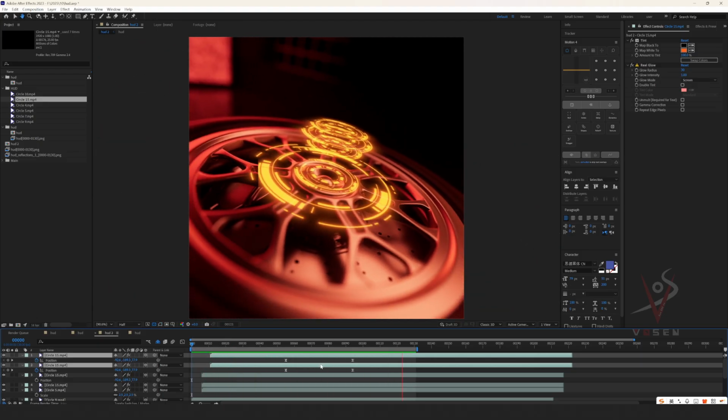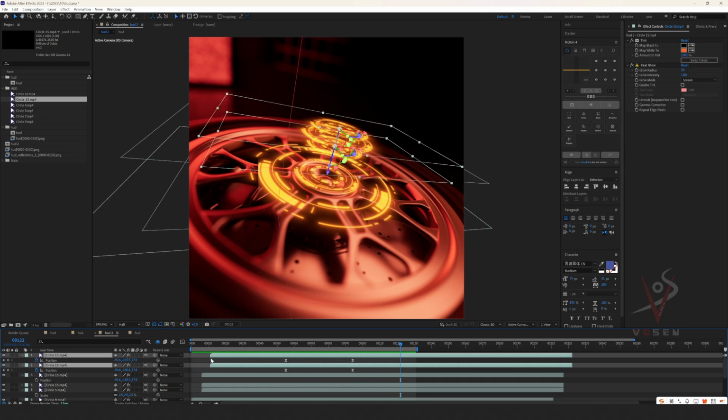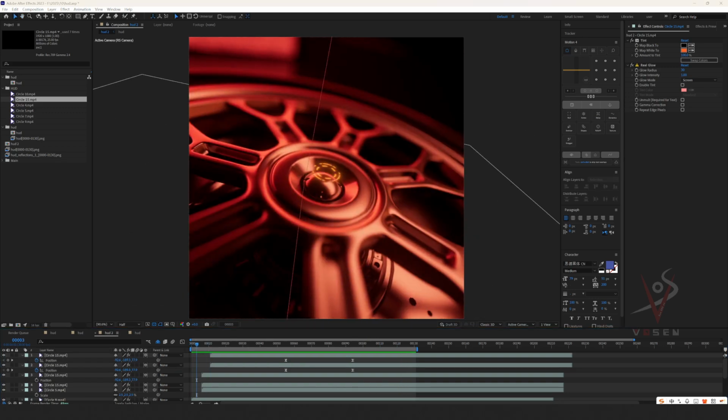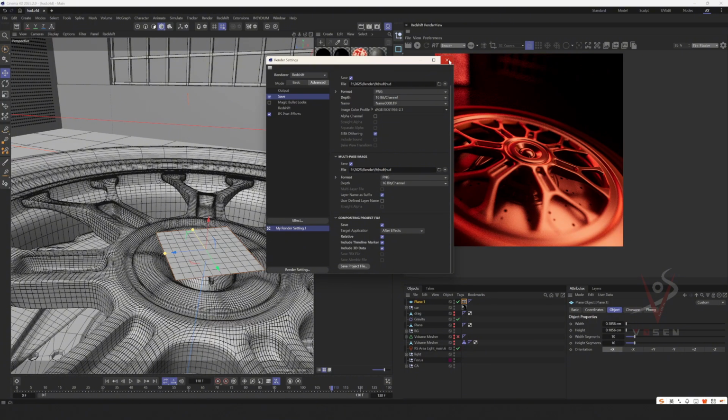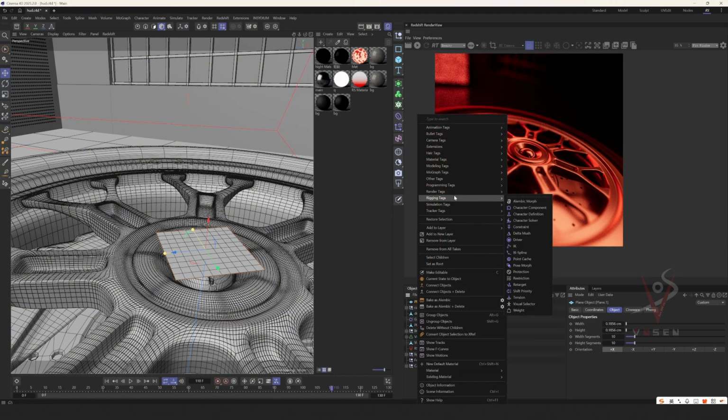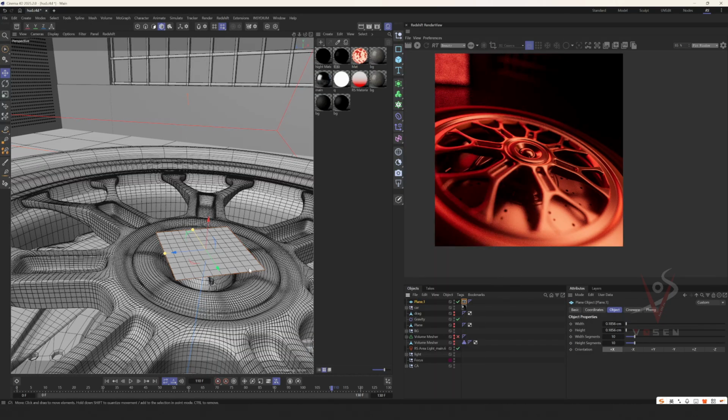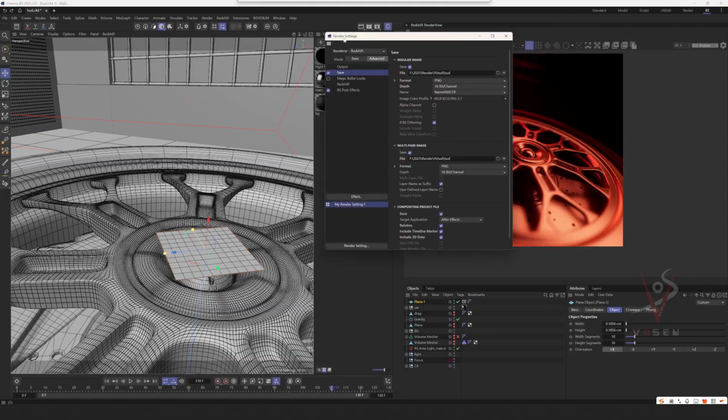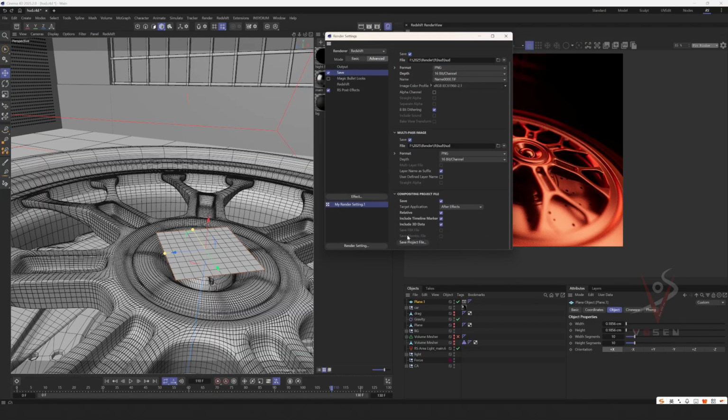OK, let's summarize briefly. One is to right-click here to render. And add this label here. And then use it as a positioning point after exporting. Then, check all these options in the Save section. Then save the project file. It will export an AEC file.